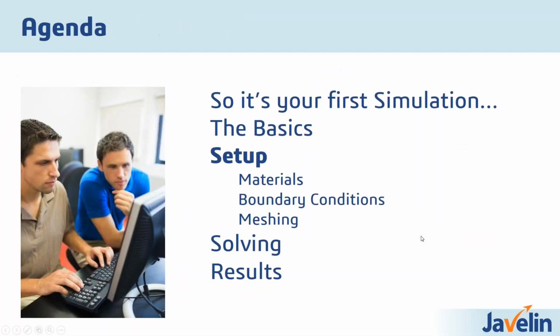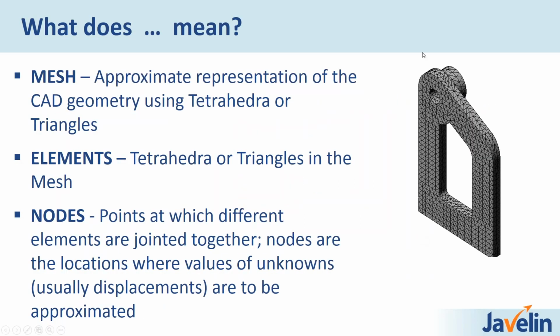And there we go. So the one final thing I'll mention, you'll hear me refer to mesh, meshing the model, creating a mesh, refining a mesh. Well, mesh is the term we use to collectively describe the collection of elements and nodes in the model. So when we mesh a model, using it as a verb, we're talking about creating the elements out of it. If we're talking about, well, show the mesh, I'm talking about showing what we're seeing right here, the representation of the mesh. If I talk about refining the mesh, I'm talking about making it smaller or more detailed in some areas. So with that basic terminology, we can move forward.